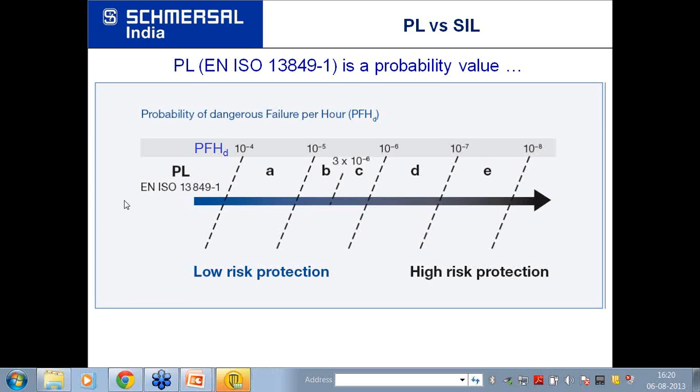But nowadays most of the electronic devices have quite a wide band of voltage available. So one way is to definitely have a good backup for the system, like providing fuses or short circuit devices. And the second is to have wideband operated electronic devices, like a safety relay, which can be operated from 48 volt to 230 volt AC. So this kind of devices.